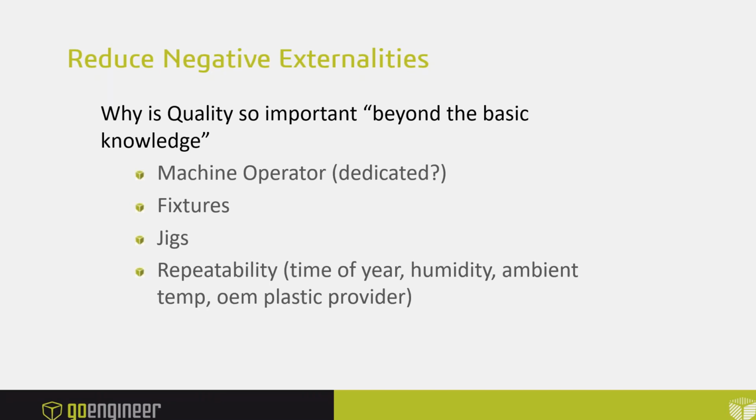Bummer, right? Negative externality. Maybe not only that, but you also have to pay for jigs and fixtures to hold those parts flat, to keep them the way they were designed, straight or flat or whatever it might be, because maybe your gate location is not optimized. The other thing is that repeatability is a huge issue a lot of the time.